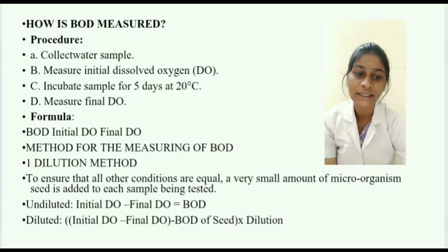Place the tubes in the preheated reactor and digest at 150 degrees Celsius for 2 hours. Allow the tubes to cool to room temperature in a rack and then take the measurement. Transfer the cooled mixture to a flask. Add ferroin indicator. Titrate with ferrous ammonium sulfate until the color changes from blue-green to wine red.